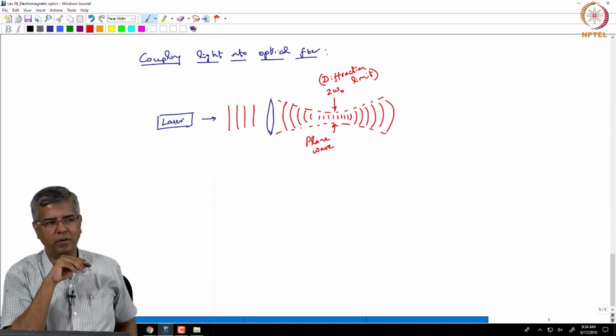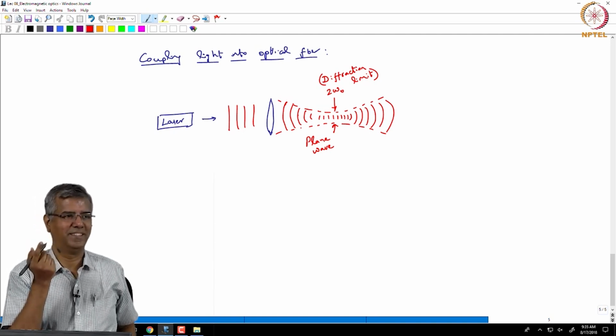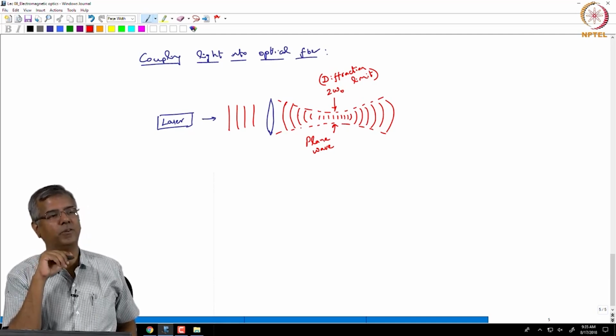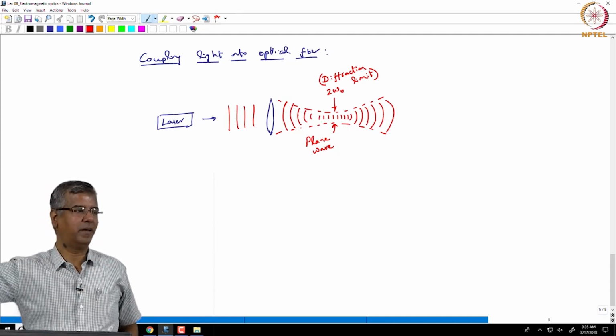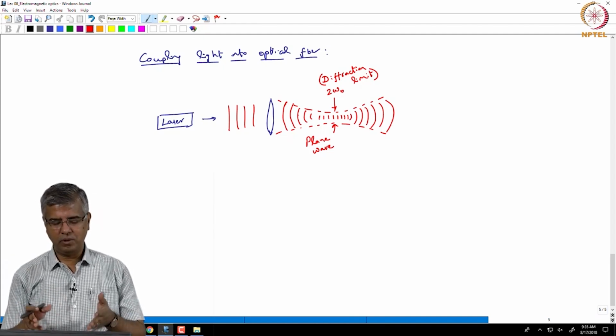What can you say about the wave vector for the single mode fiber? How many wave vectors does a single mode fiber represent for the light that's propagating? Well, it's single mode, so it has to be one wave vector, and that's going straight down the center of the waveguide. So what does that constitute in terms of the wave fronts? It's a plane wave front, right? So what you have in a single mode waveguide is actually a plane wave front that's moving all the way across.